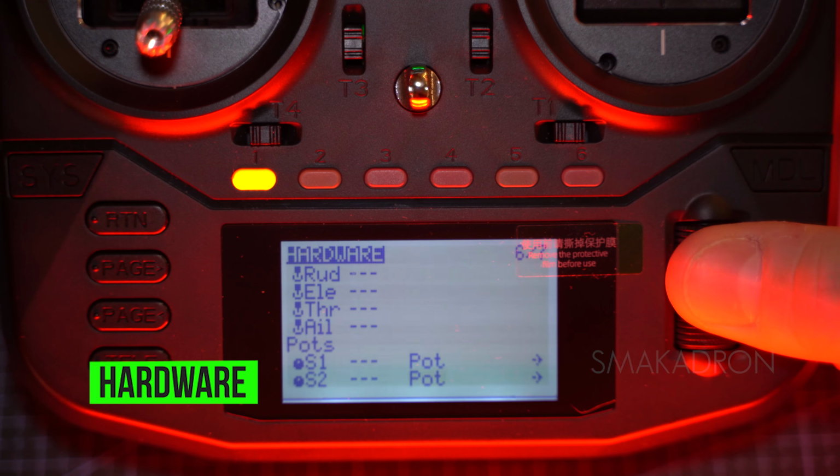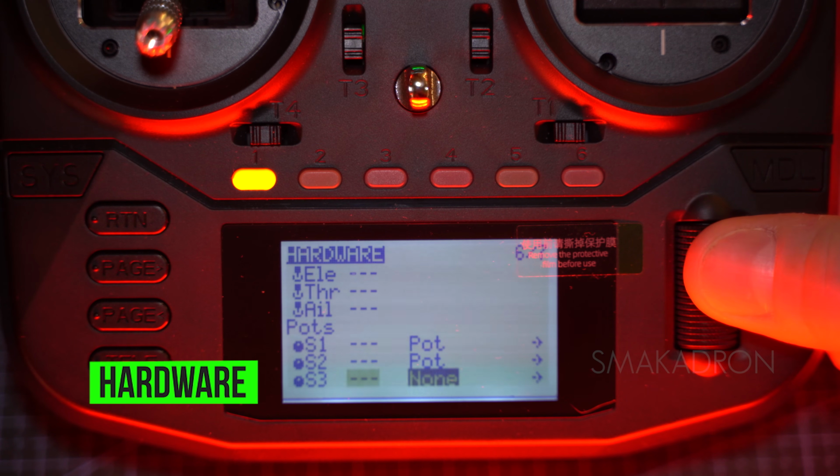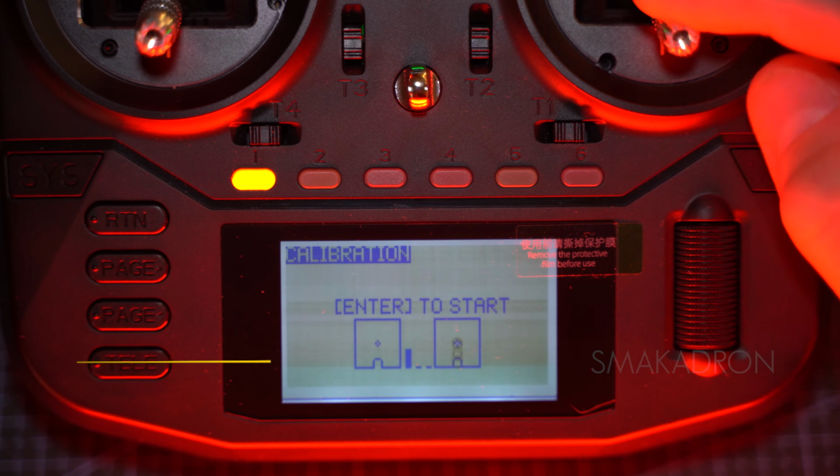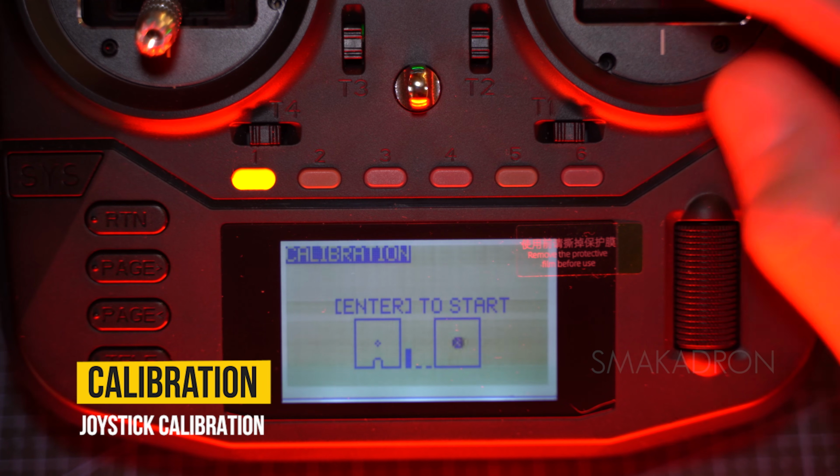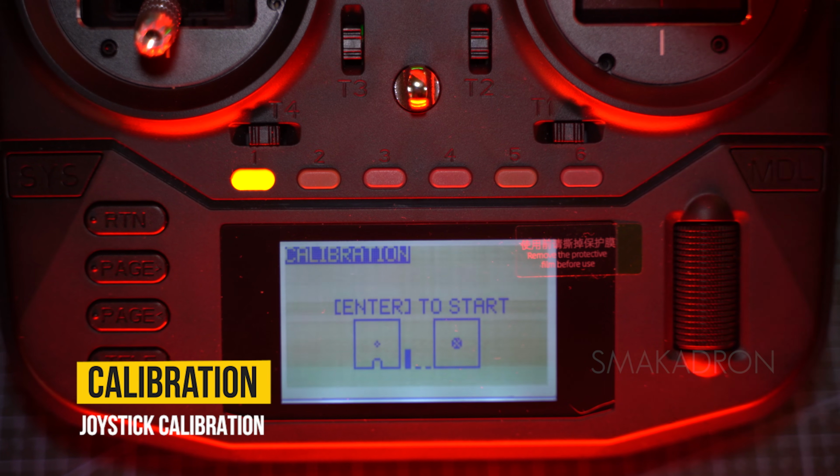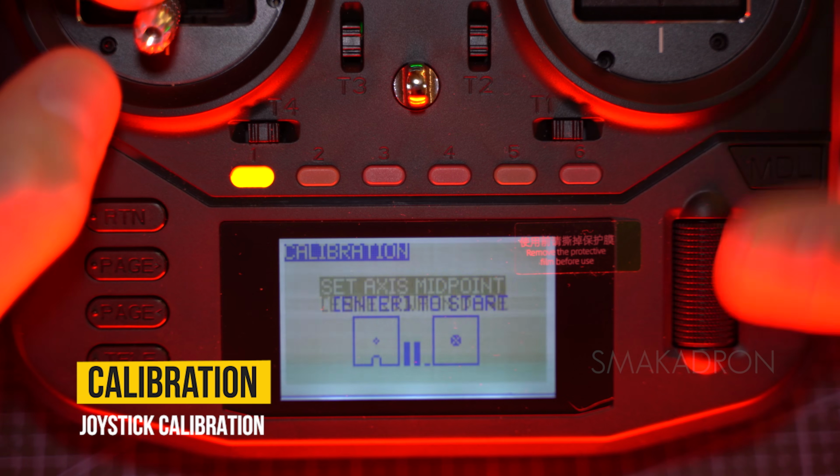On my radio, S1 is a rotating slider. S2 is the same. S3 for me are separate buttons that I will use for switching something within a range. For stick calibration, use left to right and bottom to top movements, not circular motions. Also, use a normal level of pressure at the endpoints. Excessive pressure at the endpoints can lead to incorrect stick calibration.